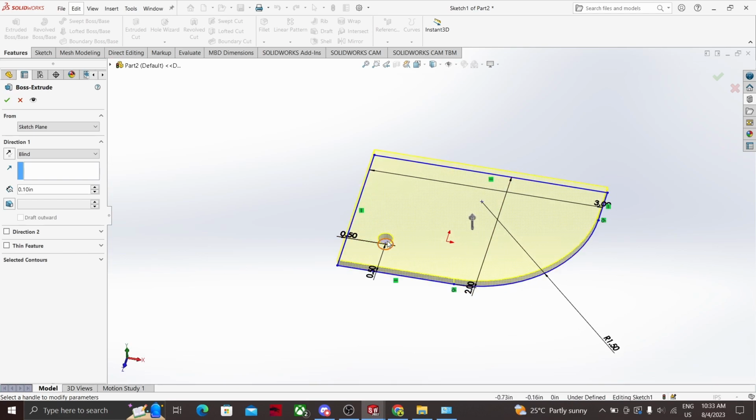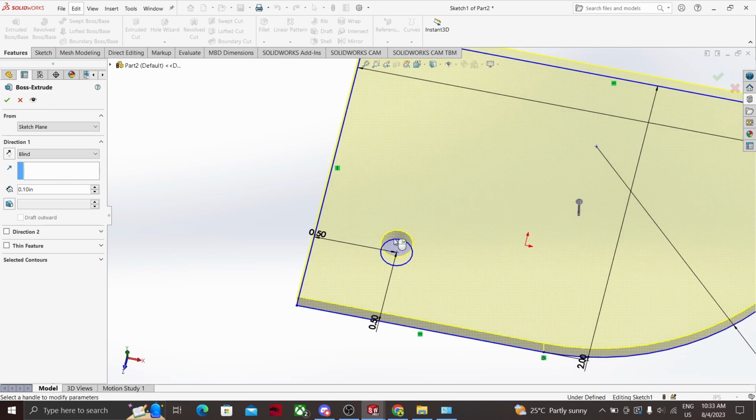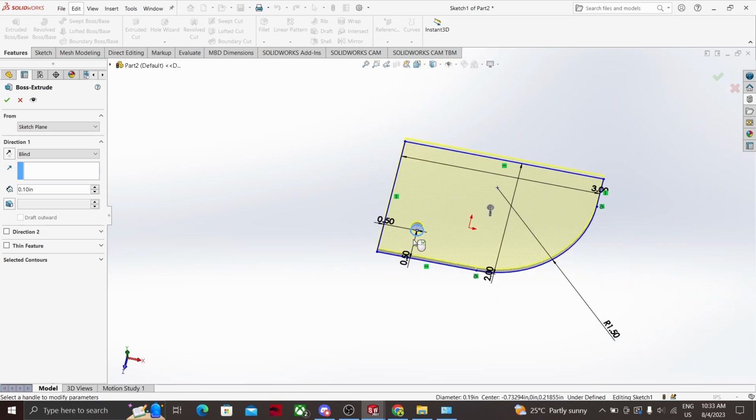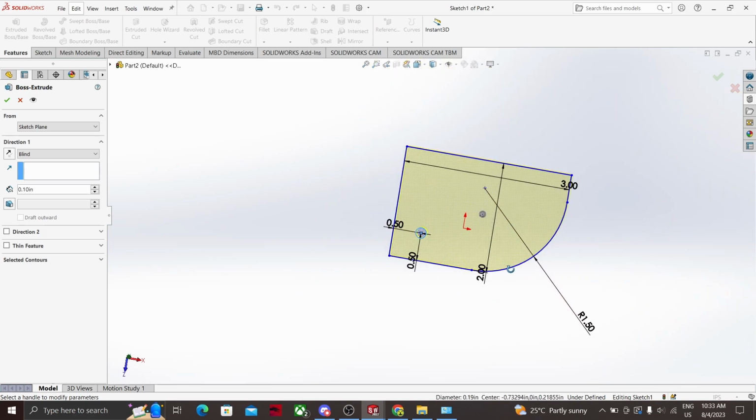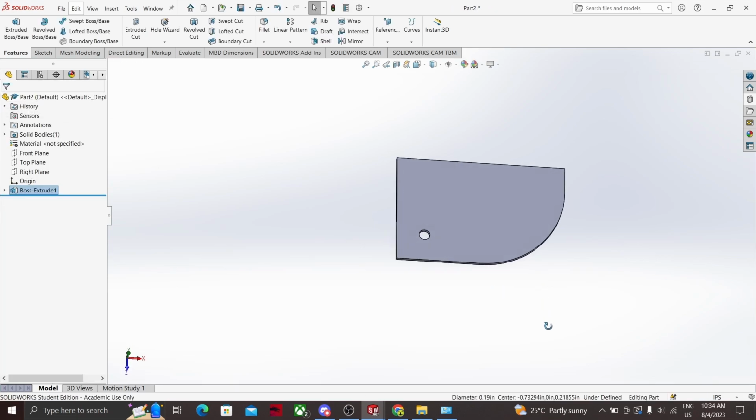You want to make sure that these screw holes are hollow, so you can see that this is hollow, because sometimes it's like this, right? And we want the screw holes to actually be hollow, so we can just click it again. There you go. So now we have the screw holes hollow, and so we can actually determine the height of it right here. I think polycarbonate is like 0.0625 inches, like that. And we can just click the check mark. So now we have a part.